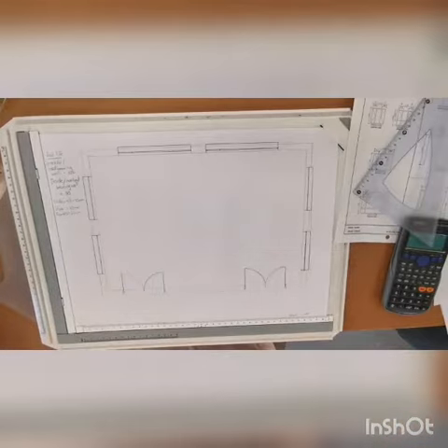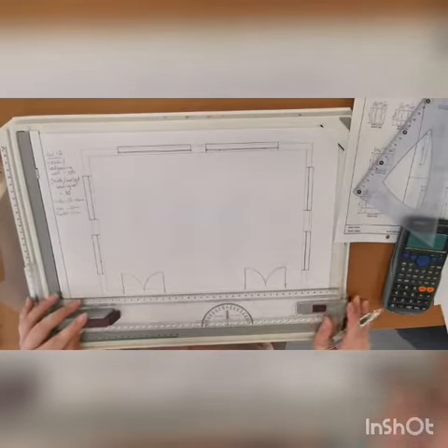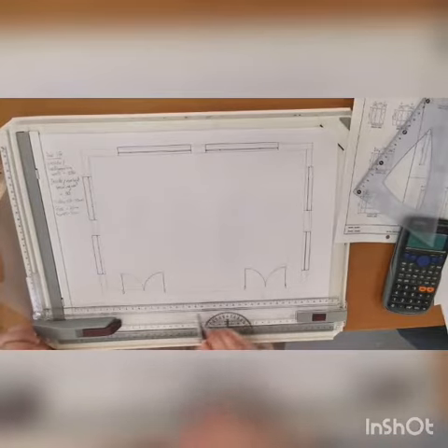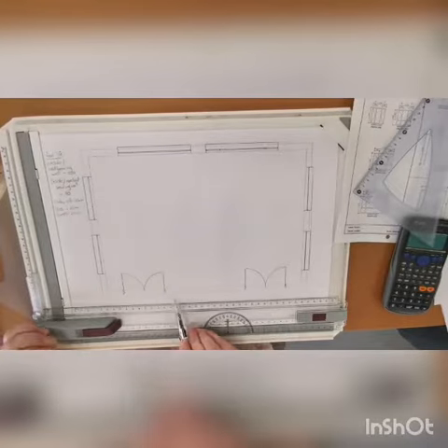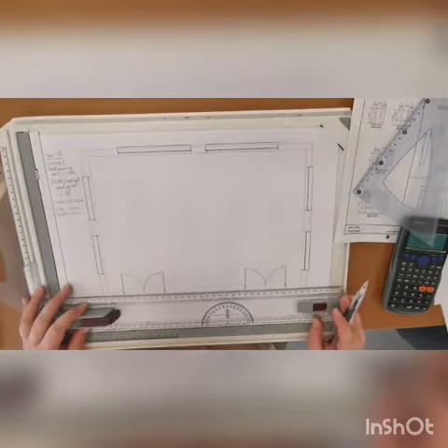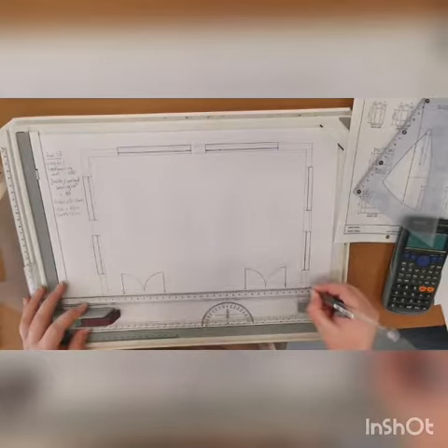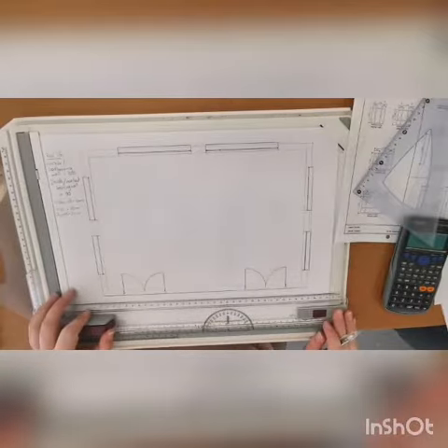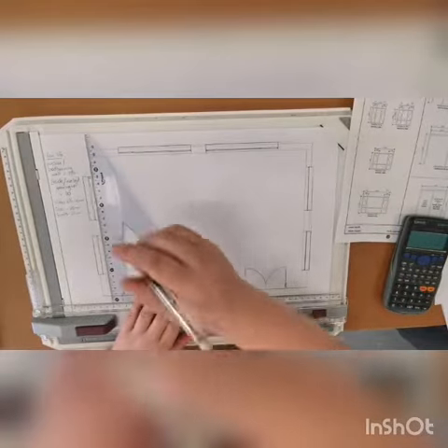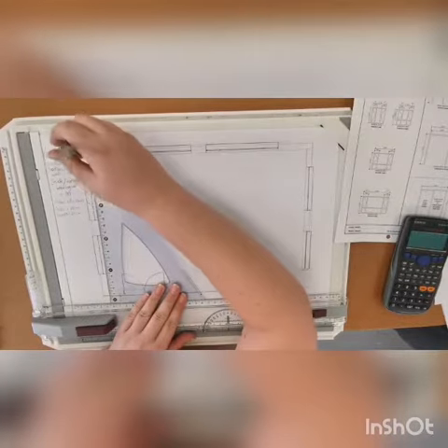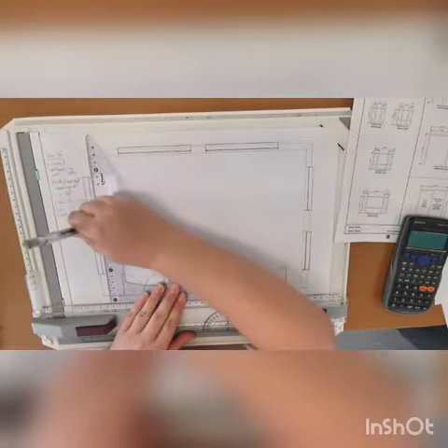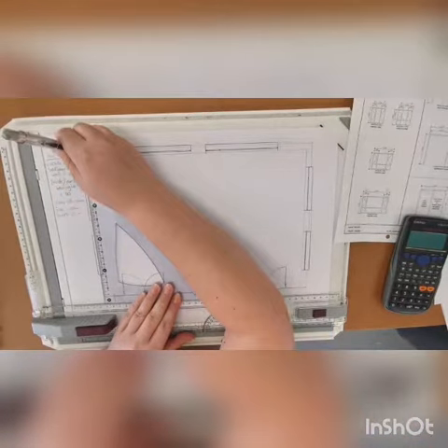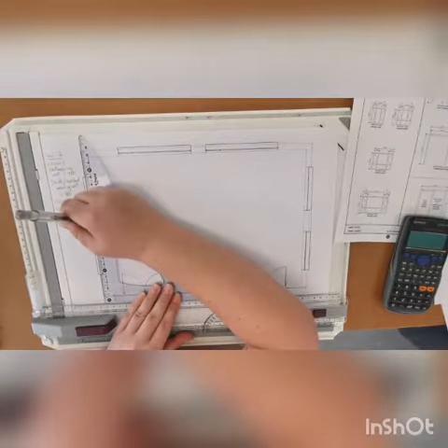Now we can make sure that all our walls are dark where they should be. Any door that faces the outside of a building, we keep the outside line. Remember, we don't draw dark through the windows because that wall piece is not shown through a window.